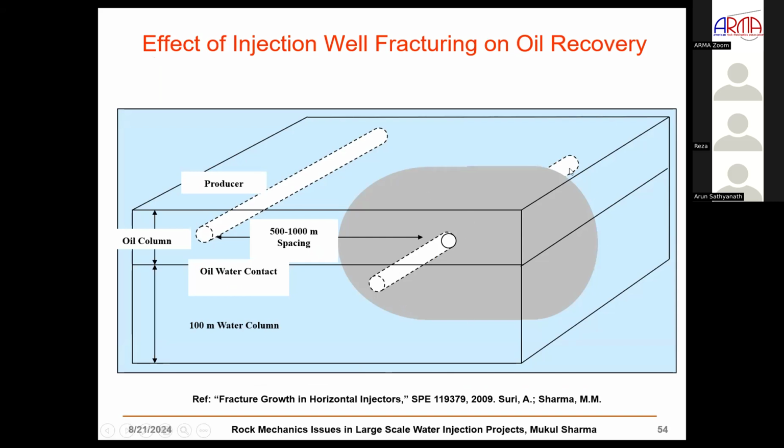So this is a field study offshore Canada, where there was a producer in the oil leg and an injector in the water leg, and this is the oil-water contact. And when they first came to us, they basically asked us, how clean should the water be? How should we treat the water so that we can inject over long periods of time? And when we did all the modeling and so on for them, we showed them that there's a good possibility of fractures being created, injection-induced fractures being created.